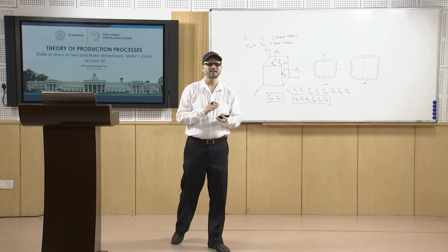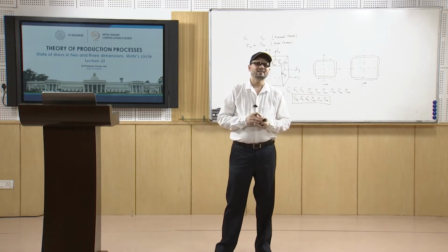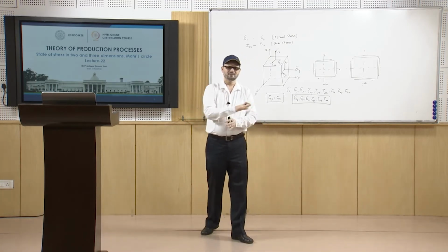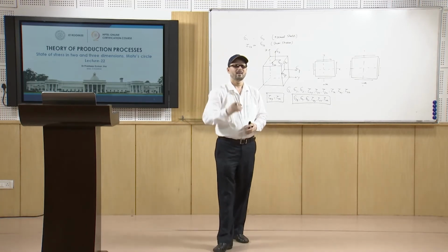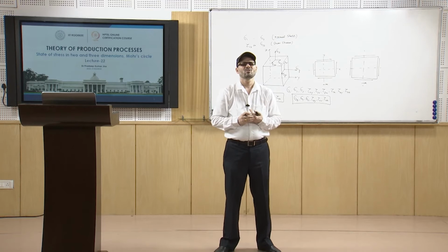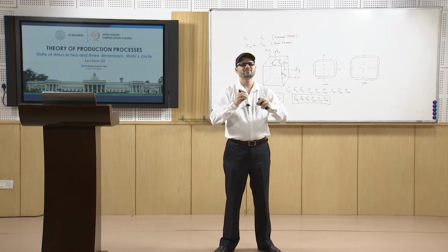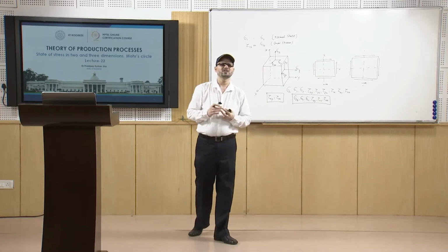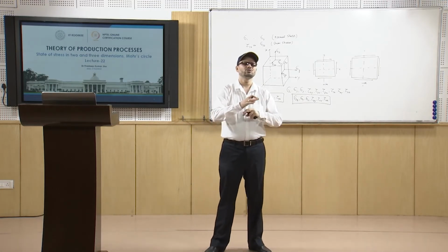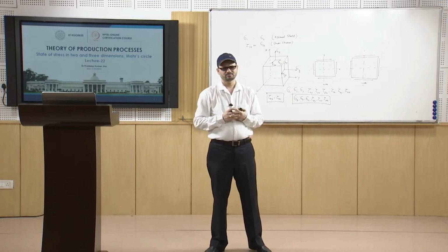Just like a very thin sheet of metal, the stress in the direction normal to the flat surface is considered very small, so you do not consider it. Once you neglect the z direction, you have the analysis in 2 dimensions. That is known as the plane stress condition.